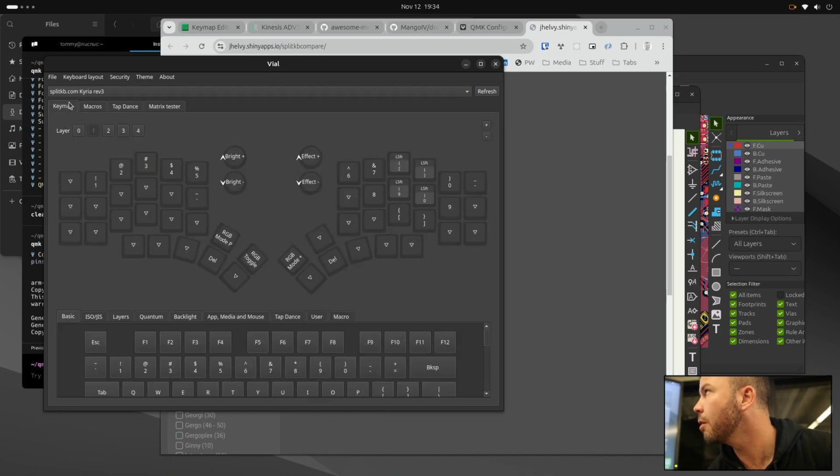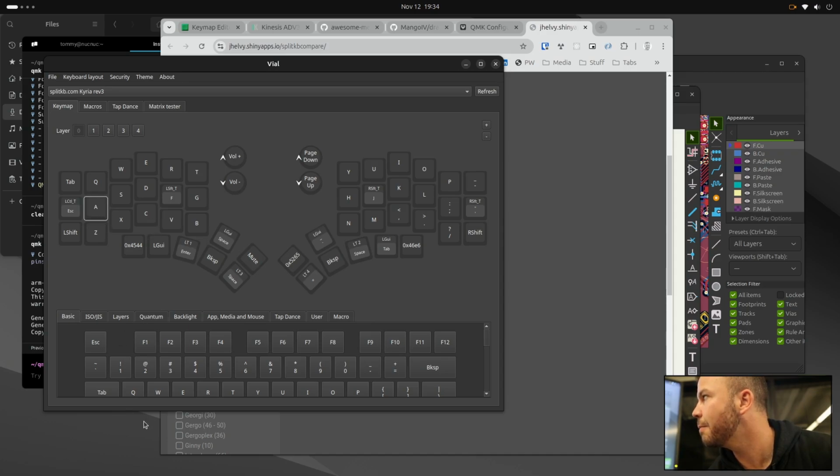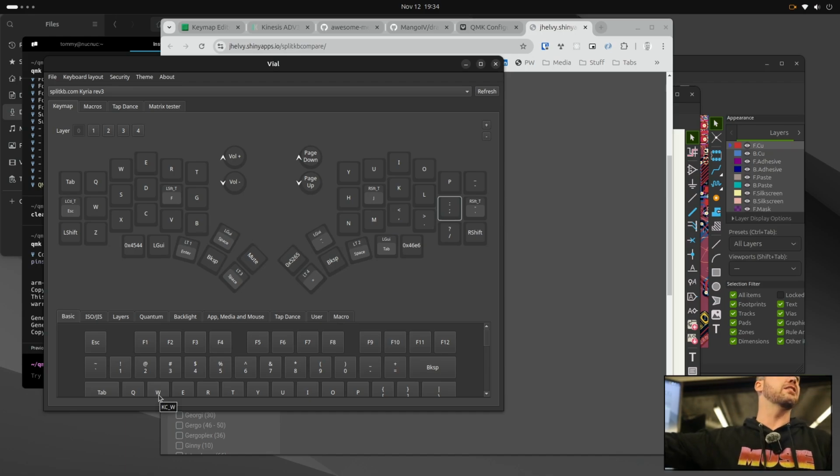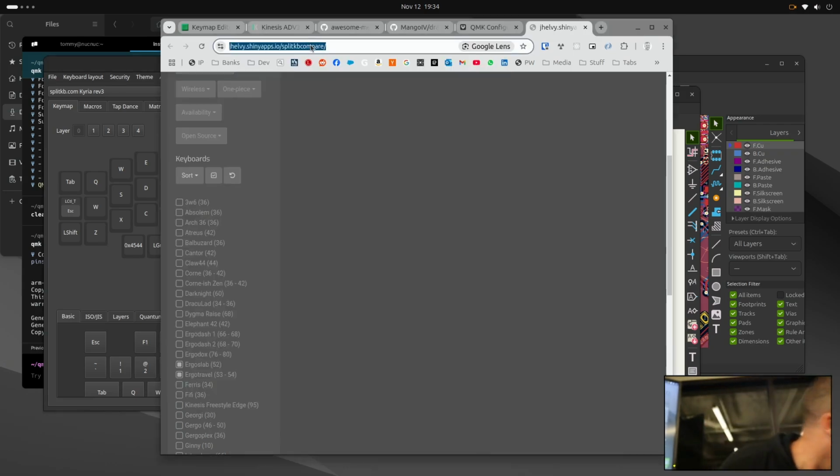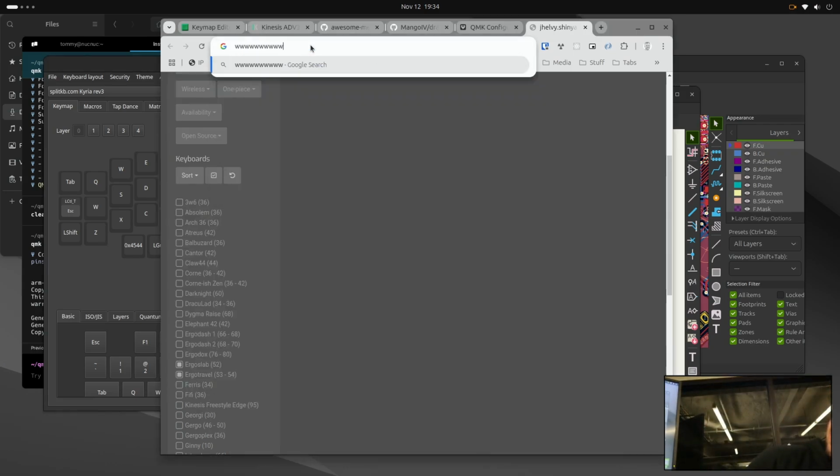And then when you're modifying these things, you just select something. Now that A key is a W, and then you just flash it, and then the keyboard is like that. Although with Vial, it doesn't need to be flashed. It changes it as soon as you say upload, which is kind of cool. Sometime later, you're going to type that A key, so I wonder why it's W. Later I'm going to be like, man, someone's messing with this. But it's that easy with Vial versus QMK.